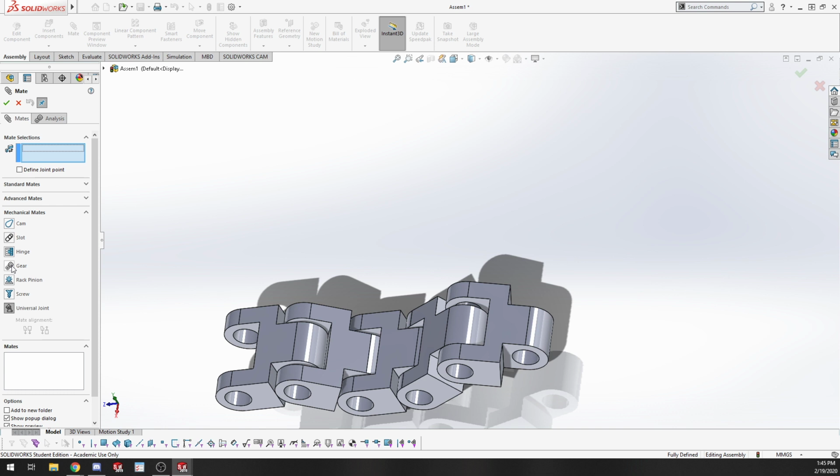There's also, within that gear mate, I'm pretty sure, or no, that's another feature within SolidWorks. You can actually build belt systems natively within SolidWorks, and you have all your pulleys that you select. It calculates a belt for you. You can switch which side of your pulley your belt's on, gives you the length of it. You can add tensioners and that kind of stuff, which is super cool. But kind of that same principle. You're defining things based on certain ratios, certain diameters.